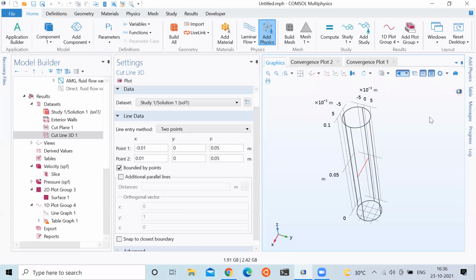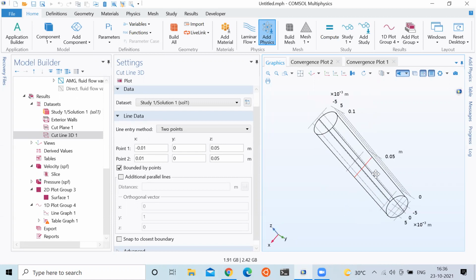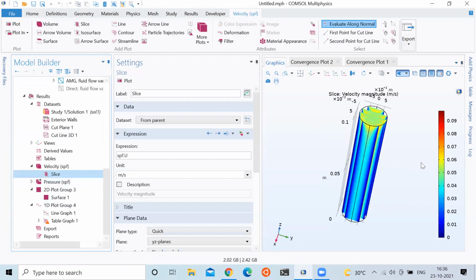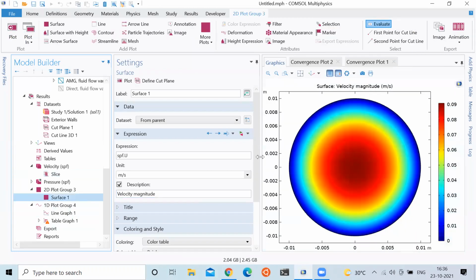You know the temperature is varying only in the x direction. So why make the entire cuboid? You just take a line and you vary the temperature by applying the boundary conditions. That is how people usually simplify their problems and avoid making 3D. But in 3D, you get all these visuals of how it is exactly varying. These 2D plots you get are not what you will get in 1D. So that is the advantage there.